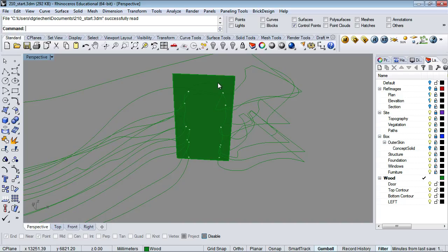So everything that is built, generally, it's a little bit easier if we can always go around and define what is X, Y, and Z relative to this complex 3D geometry. So what we can do is create a plane, and we can tell Rhino to say, we want this to be the construction plane. This is the surface. This is the X, Y coordinates that we want to start to create geometry on. Okay? So this is really handy when we're doing cross-sectional curves in complex geometry.